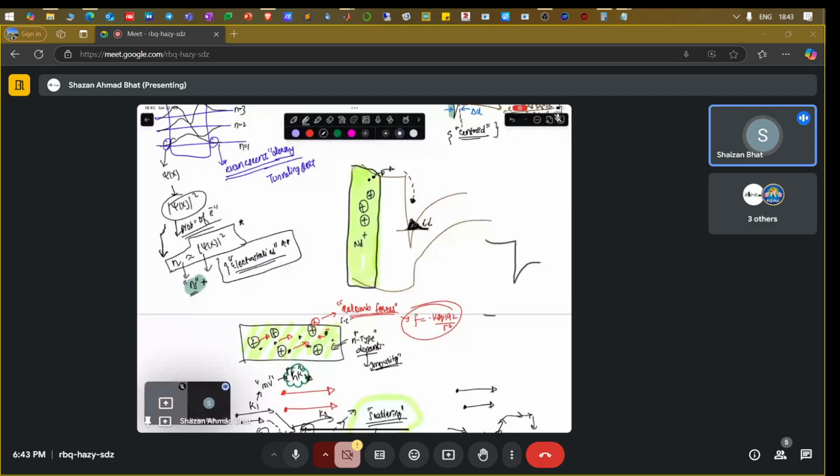Then you would have positive charge, positive charge, positive charge, which come from the donors, and electrons here. Because there is a channel of the electron sheet, the sheet charge, whenever the electron moves, it would face these scattering events. The electron is going to move in and out of the screen, not in the right and left direction, because there is confinement there.